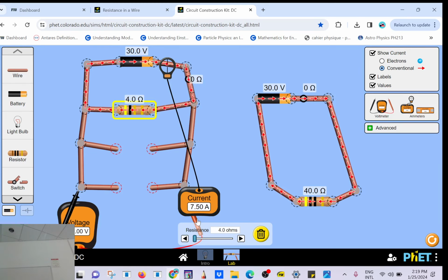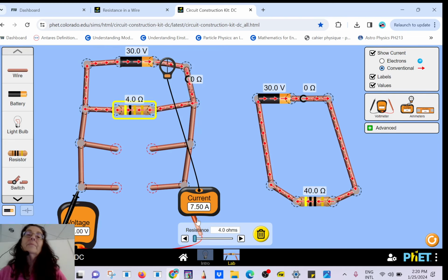Everything is clear? So you have 4.4 we begin with, or 4.3, minus the voltage across the internal resistance, and then minus the voltage across the load. So the load is not happy, okay? It doesn't get everything it was promised. Plus I have also resistance across the connecting wires. Okay, so let's go back to here.